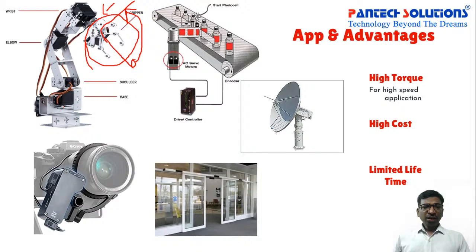Similarly, if you take this requirement, see here that this elbow mechanism should change its position in a very quick manner. In that aspect, we have to keep some DC motor with minimum gear requirements, so that the speed will be high. And again, reliability is there, and noise is there. So we have to choose the motor accordingly, so that the noise is very, very low.